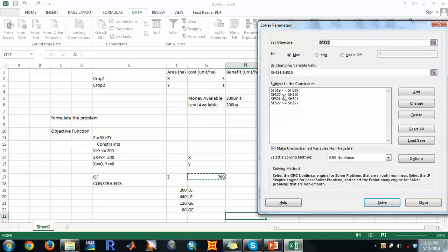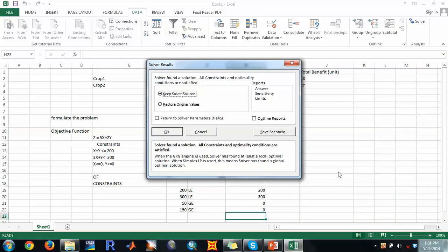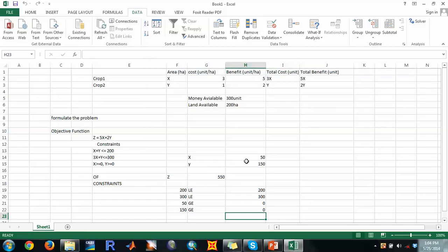Check the dimensions and the values you input here. If they are correct, you can use the Simplex LP method. You might learn the details about the simplex method in water resource systems. The simplex method will do the iterations and solve the problem you created. So say OK, then you can see the results.